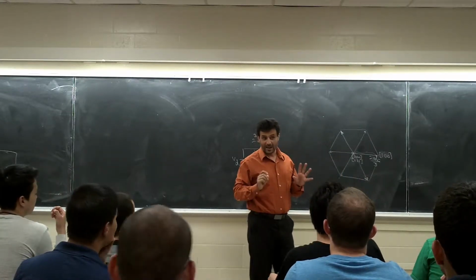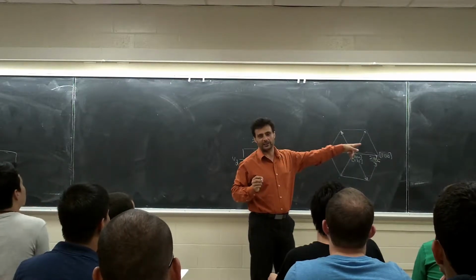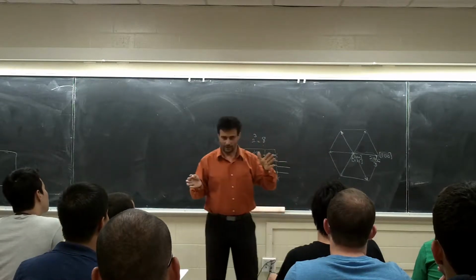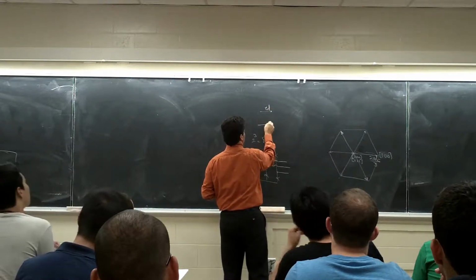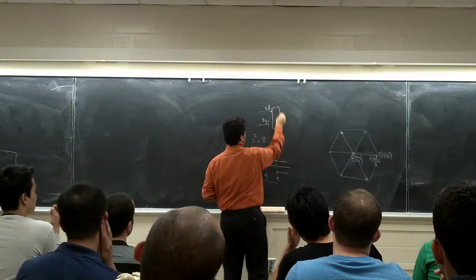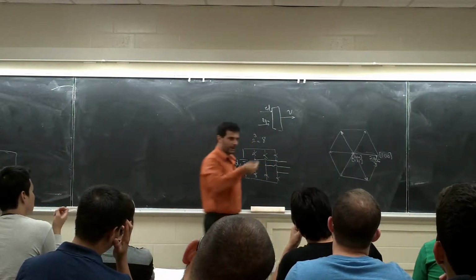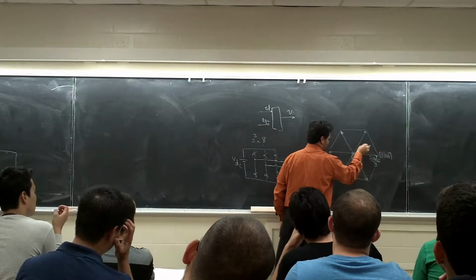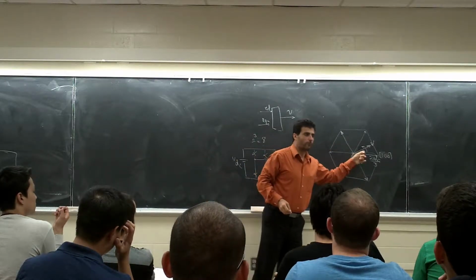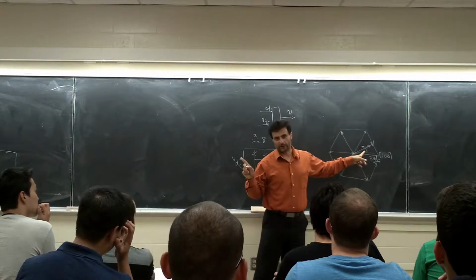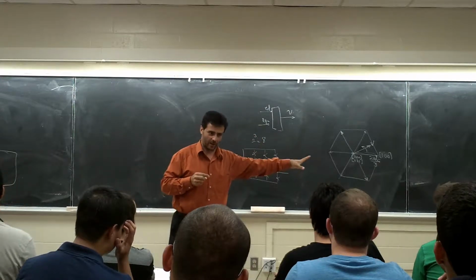But about a space vector, the voltage you need, we talked about Ed and Eq, remember, we said before I normalize it, right? I have an Ed and Eq. If I convert this using the DQ, I'm going to get my space vector, they call it V. So this vector is rotating, you know what I'm saying? This is what the inverter should ideally generate. This is what is coming from the control loop, right? It's this much voltage, this much phase.